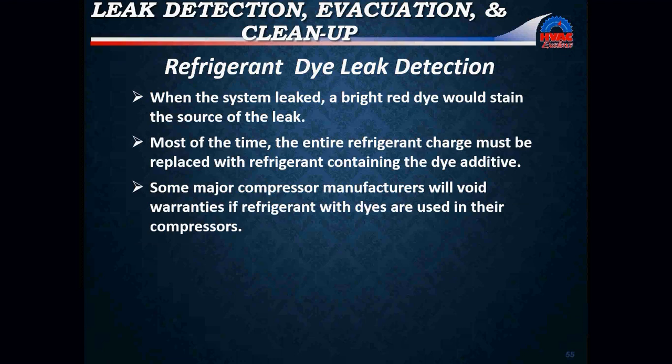When you're dealing with refrigerant dye leak detection, when the system leaks, a bright red dye would be used to stain the source of the leak. Most of the time, the entire refrigerant charge must be replaced with refrigerant containing a dye additive. Some major compressor manufacturers will void warranties if refrigerant with dyes is used in their compressors.